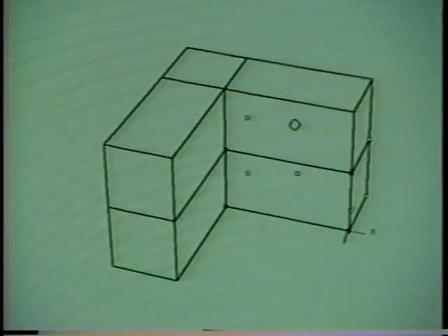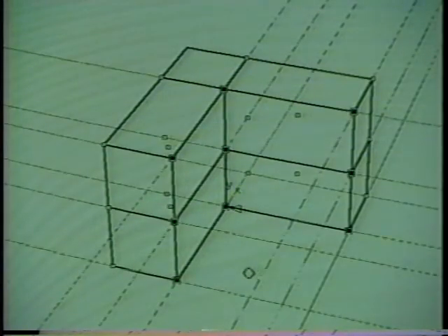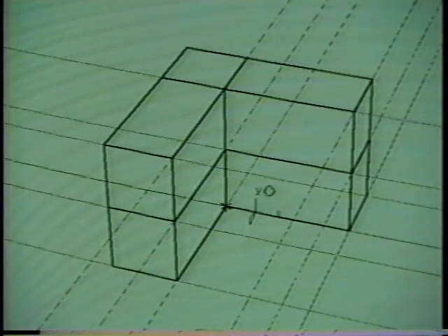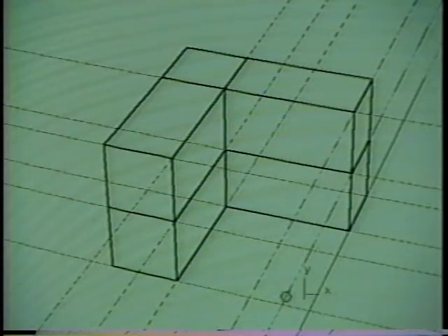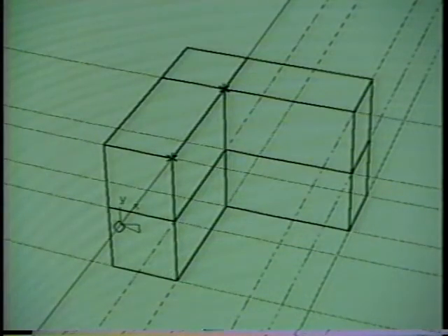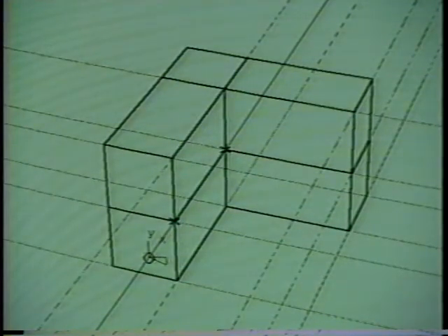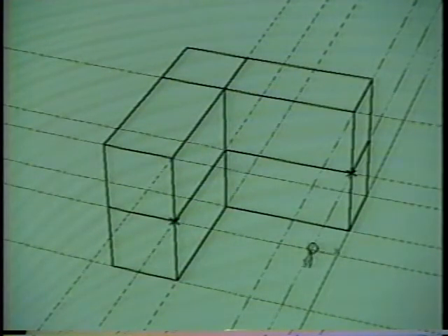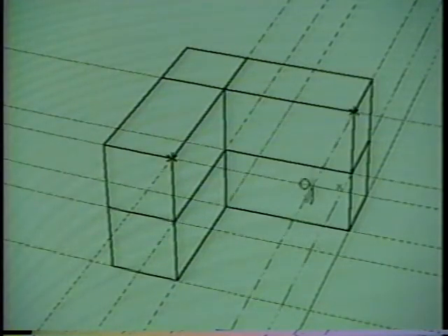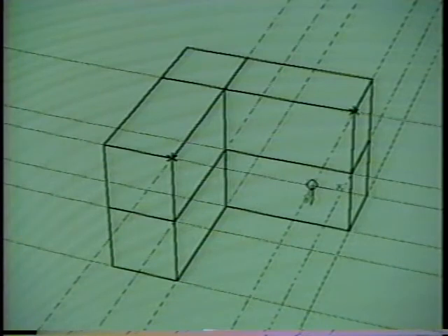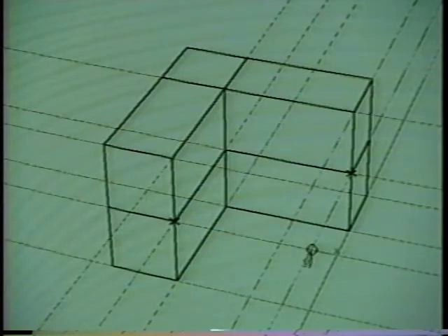Even with perspective, it can be hard to tell how deep in the scene an alignment line is and to pinpoint the vertex that triggers it. When the skitter snaps to an alignment line, Gargoyle 3D draws a starburst to highlight the vertices that trigger that line. Here, we see that this alignment line is triggered by vertices at the top of this wall of blocks, while this alignment line is triggered by the second level. In addition, when I snap to an intersection point, vertices that trigger either of the intersecting lines are highlighted. For instance, 2 starbursts appear when I snap to this intersection point or to this one.